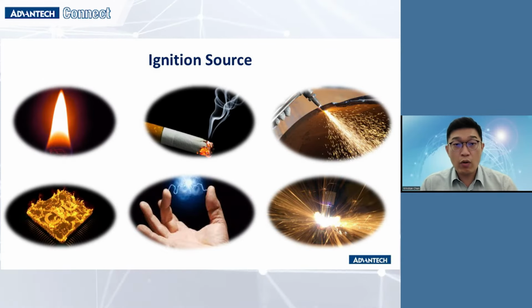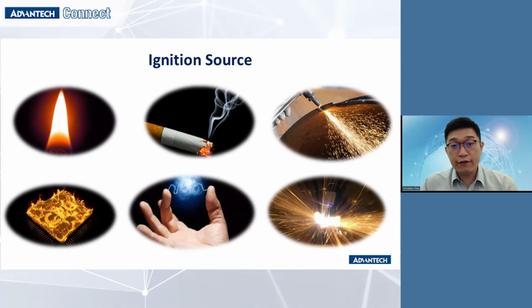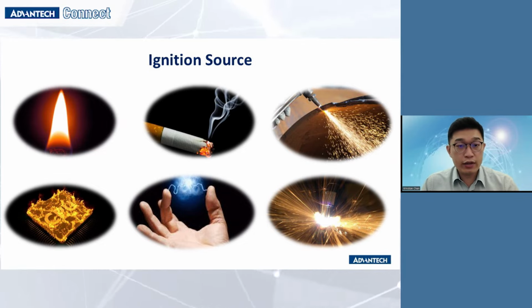Let's see what our ignition source is. People used to think ignition source means fire or spark. The definition of ignition source should be a source point with high energy density, not only fire sparks, but also smoking, welding, and cutting. Hot surfaces and static charge can cause an explosion.